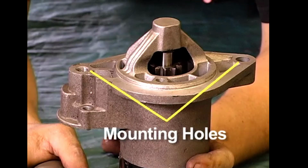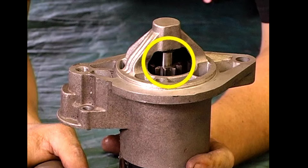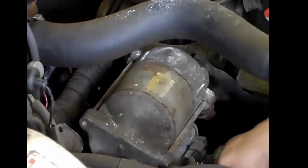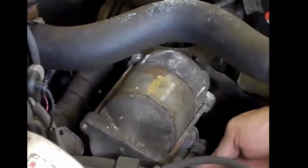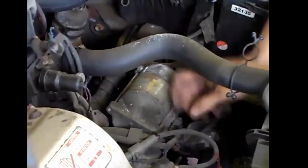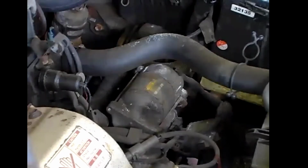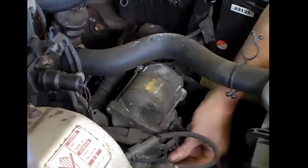Large holes in the thick drive end frame are provided for bolting the starter motor to the engine. An opening is provided so that the pinion gear can engage the flywheel ring gear. Here, you see a starter motor attached to the side of an engine. The starter normally bolts to the engine block or to the clutch housing. A strong mounting of the starter motor is needed to keep the pinion gear and ring gear meshing quietly.